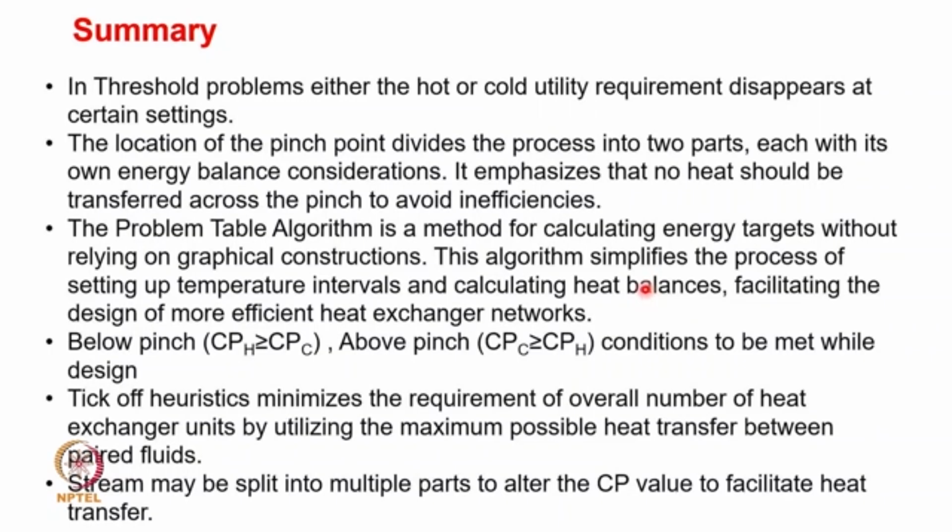The problem table methodology that we have learned here is a methodology that helps in calculating the energy targets without relying on graphical constructions. The algorithm simplifies the process, setting up temperature intervals and calculating the heat balances, facilitating the design of more efficient heat exchanger networks.